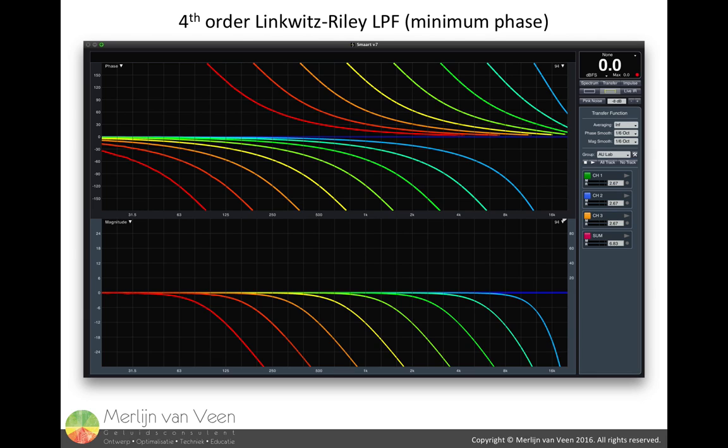So let's look at band limiting exclusively, without introducing the typical phase shift, by resorting to linear phase filters instead. Filters that maintain a linear flat phase response regardless of the magnitude response. Smart runs natively at 48 kHz. So this gives me a full range bandwidth of 24,000 Hz, half of the sample rate.